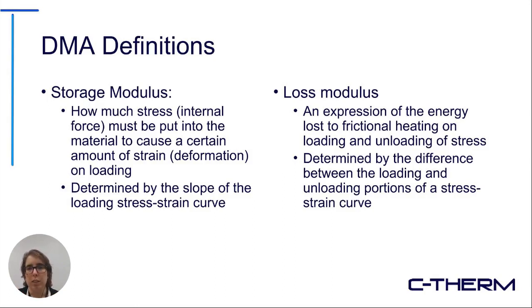The loss modulus, on the other hand, is an expression of the energy lost due to frictional heating during loading and unloading of stress. You determine that by taking the difference between the stress-strain curve on the loading and the unloading portions of a measurement of a material.